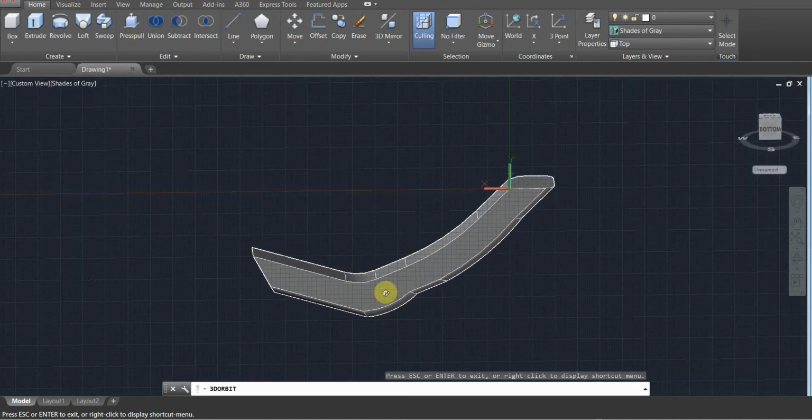Also, we created an extrusion as tapered. Can we follow the path with a taper, both of them? Yes. We explained how we can extrude with a taper angle, then we explained how we can extrude following a path. We can do both of them. We can follow a path and extrude and taper in the meanwhile.